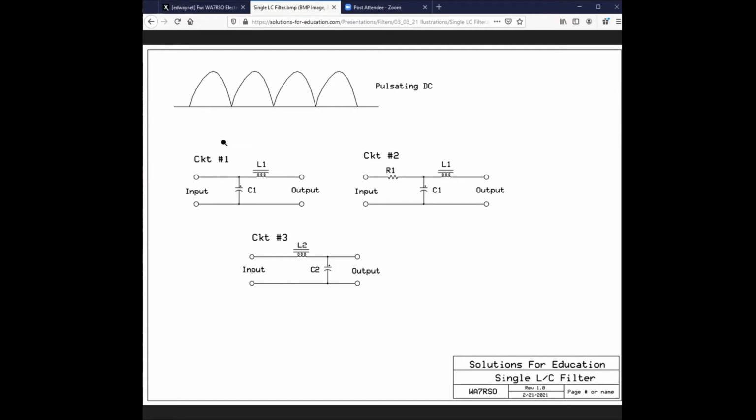So going back to the beginning, at the first instant, as the voltage starts to rise, this guy here acts like a dead short. This guy acts like an open circuit, no current. However, this guy here says, I'll take it all. So as this guy starts to charge up, we understand that the collection of electrons on this capacitor is what represents the electrostatic charge. And that electrostatic charge will be fine if you disconnected it. But since it is connected, when this voltage starts to drop, this capacitor will start to discharge. And as it discharges, it's going to have current that goes through this guy here. Don't worry about the polarity, because I'm just talking about the essence of the current flow. Now, here's another thing. There is a rate of change that is very particular in this area here.